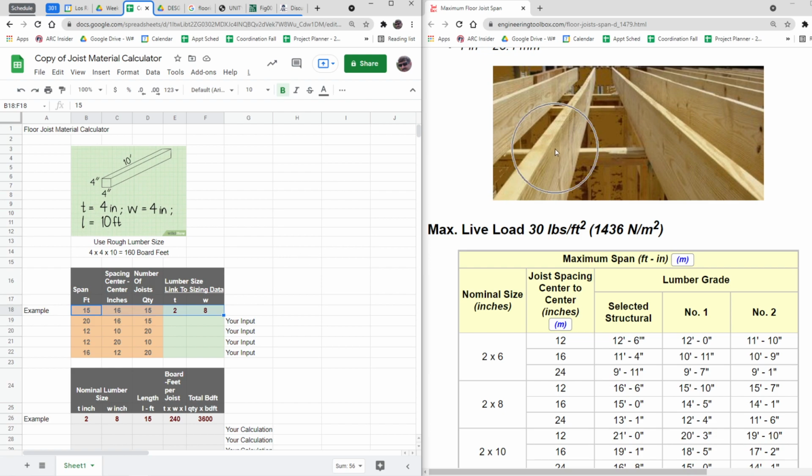Okay, and we'll talk a little bit toward the end of the class about different types of wood. You saw that there was spruce, there's fir, there's hemlock, which is a type of fir, I think, hem fir, and they all have slightly different properties, and they have different properties depending on where they're grown. If they're in the Northwest, the Central West, the Rockies, or the South, it's just because environmentally it's different.